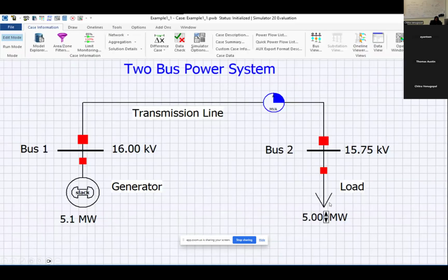We have a capacitor, a generator, and a load, connected through the transmission line, and we are changing the real power to see how much the apparent power changes, how much the real power changes, and how much the reactive power changes in the line when the load changes. This is what we have been talking about right from the first lecture, right? We will see how much it does, and then we will try to add a capacitor to this, and move on from there.